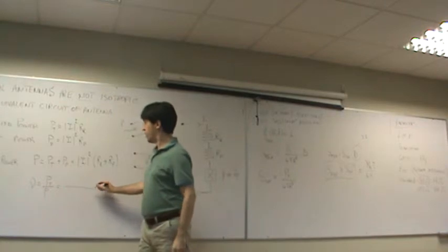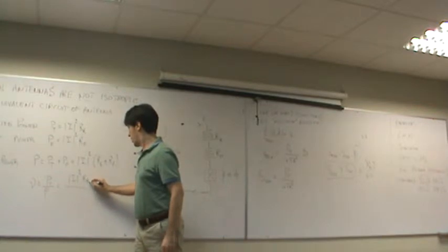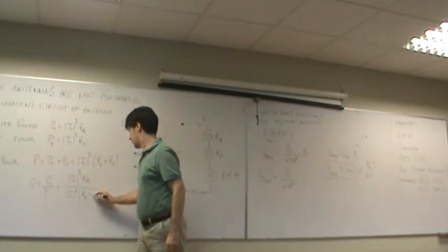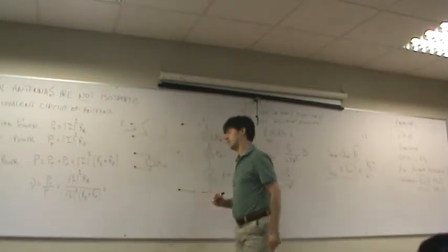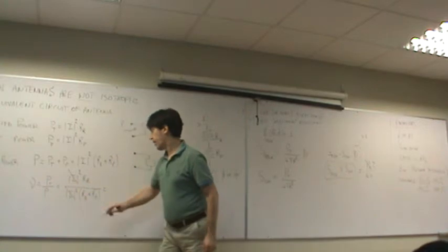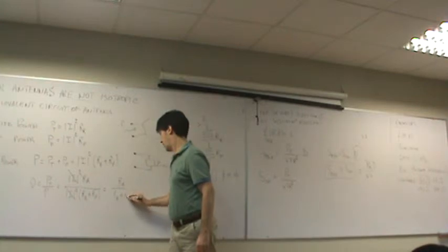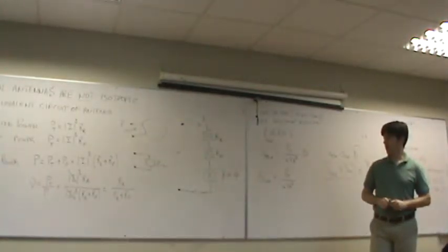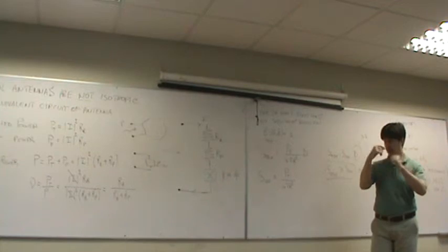So if you replace into this equation and you find out that the current... you see that the antenna efficiency is related immediately and very simply to the radiation resistance and the loss resistance and their relative ratio.